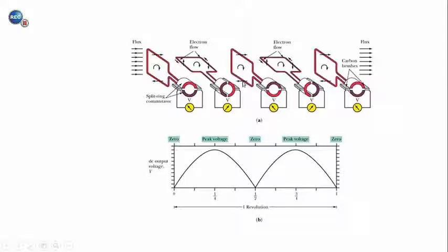And so at 1/4 of a turn, this part of the conductor connected to the red commutator was on the right brush. And so as this conductor moved down through the flux, the current was induced into the page. So the current was flowing into the page on the right through the coil and out of the page on the left. And so the current through the voltmeter is from left to right.